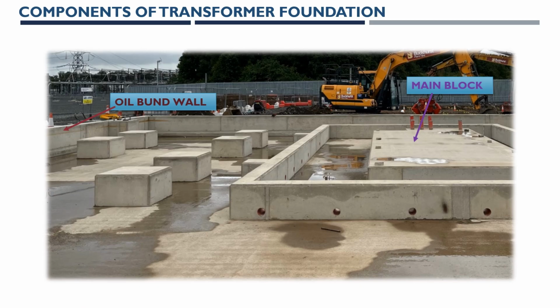There are certain calculations required to fix this oil bund wall location based upon the oil capacity and the provided technical specification, to consider the volume of oil and the rainwater accumulated during rain or storm inside the oil bund wall, which we need to calculate separately. This looks like a floor slab, which is the oil bund floor slab, where the entire oil is to be retained.